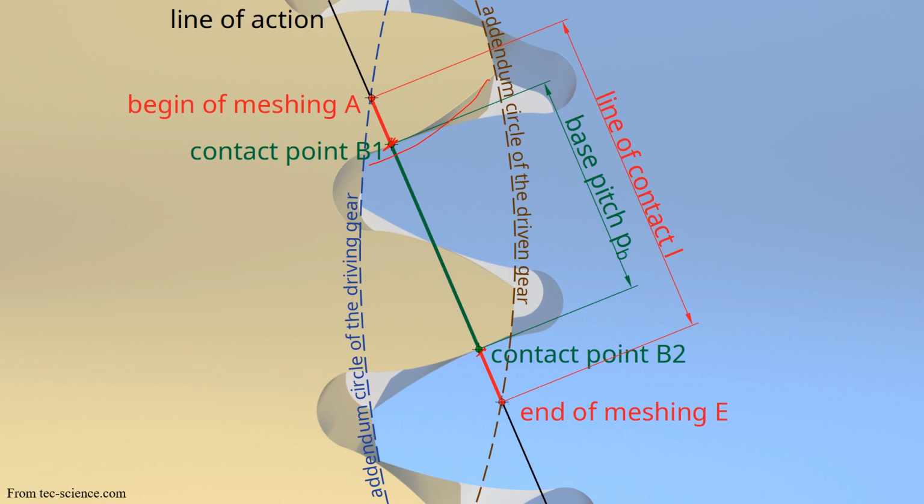Now this point is going to be moving. When this gets engaged, it means that you have made contact, and along this direction you can exert a force. But if you have only one point over here, it is not going to be an effective way of force transmission, because the teeth of the gear are going to experience much larger forces, which may adversely affect the life of the mating gears.